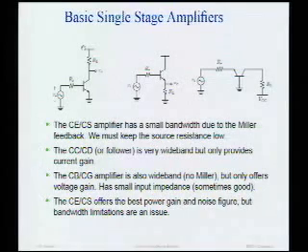So if I have this, the gain of this device is gm times R. gm varies over temperature, it varies over process. R varies over temperature, varies over process. It's not a very robust amplifier, right? If someone says, give me an amplifier that has a power gain of 10, and you give them this, it's going to vary all over the map. So how do we fix that? Feedback, right? That's right. Okay, good.